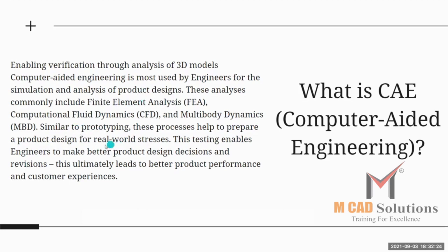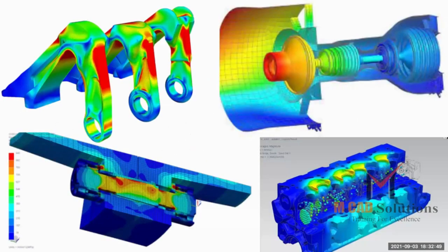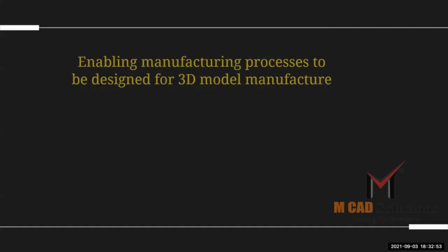So here, as we said, we apply the real world application environment, and we test our model, and we check if there is any problem. If there is any issue, we send the report to the design engineer, who modifies their model, and we do the iteration again. So simultaneous work is going on, design and FEA. On that basis, after some iterations, we get the final proper model.